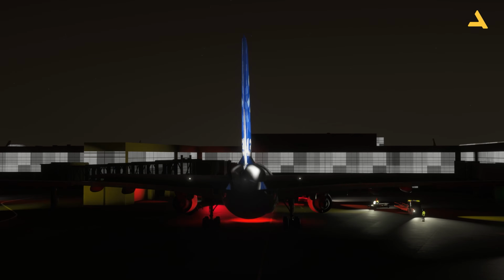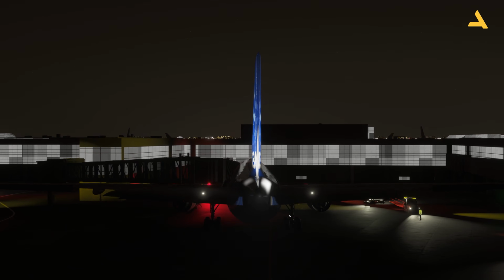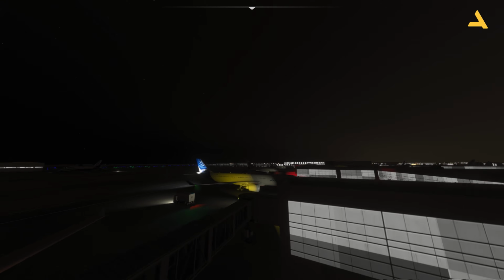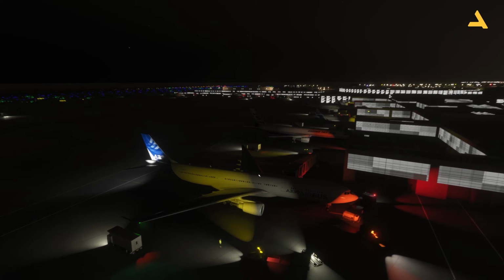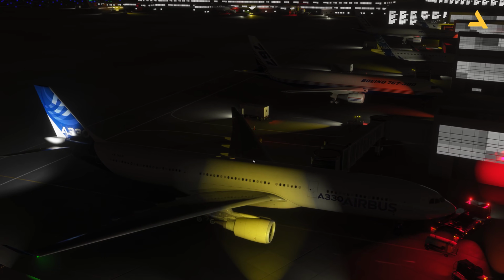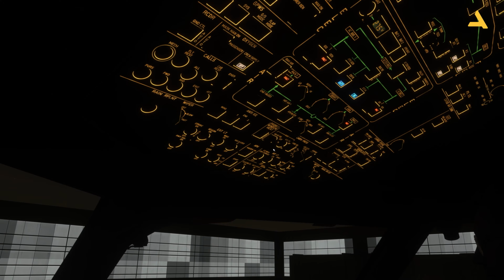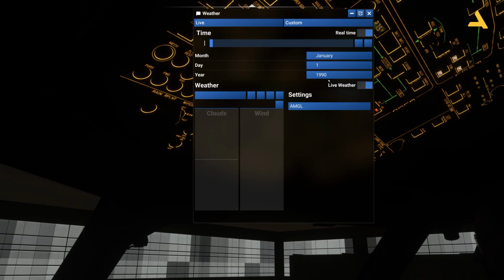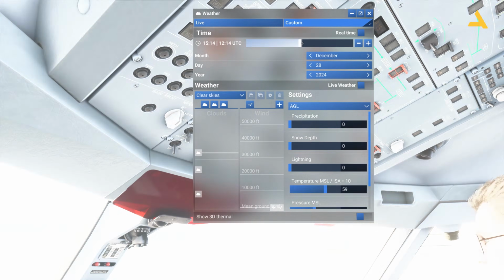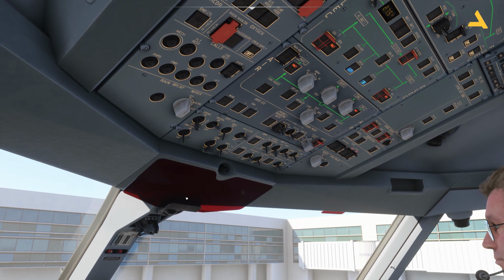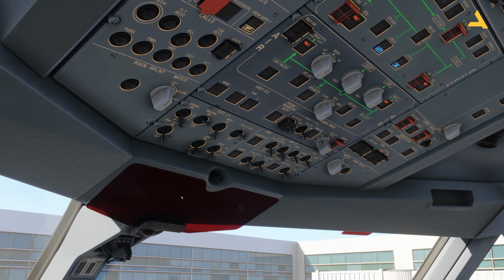And then you have lights at the back, so it means you're looking at the plane from the back. And you have the beacon. This is actually a light, which is a red light blinking over here on the top of the plane, which tells the ground staff that you're going to start the plane. So this beacon remains on throughout the flight, and plus the nav lights also remain on throughout the flight.